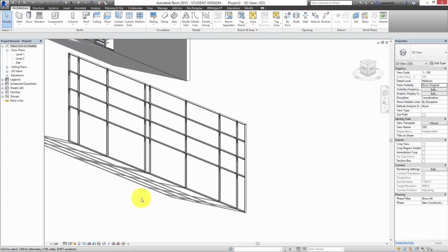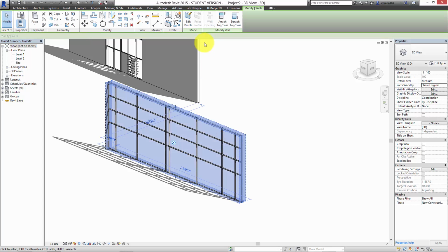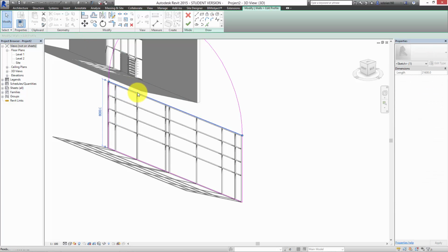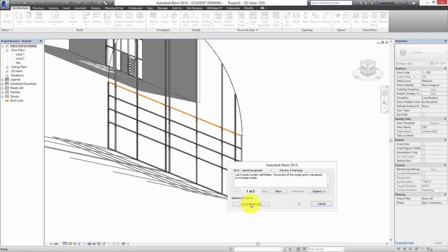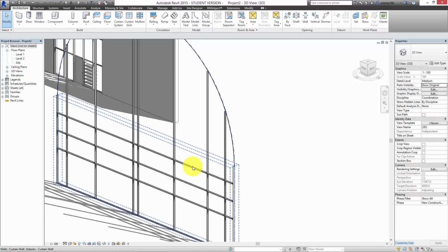Can you curve your grid lines, your curving grids, your mullion grids? Nobody's ever asked me that before. No, I don't think you can. Because in the church window, you have an arc at the top, but you can easily change that by just putting an arc on the top. The mullion. I'll show you now. But it won't curve the actual grid lines. The only way to make something with curved grid lines is to make a component, which won't be a specific thing.